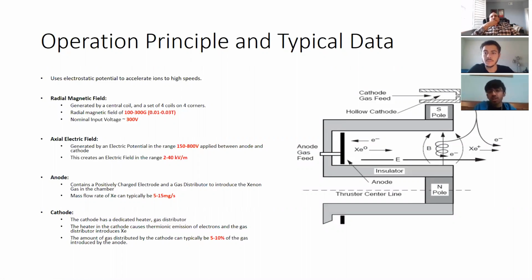Then the amount of power that goes out as radiation loss, that goes into the anode, and that goes into the channel walls, because there is an amount of power that is also lost into the walls because of the striking of these electrons and ions on the dielectric wall. So once we get all this, we can model it in COMSOL, because we will know the amount of power to be inputted into the anode surface, into the wall surface, and the amount of radiation lost.